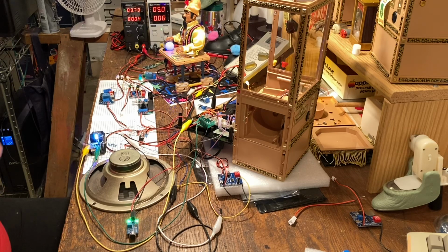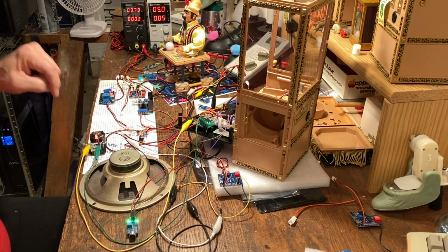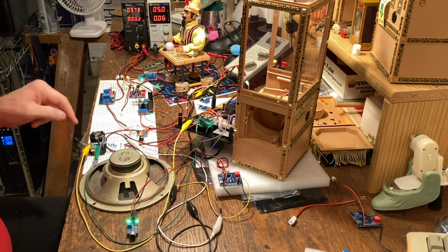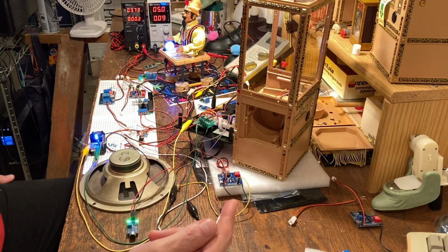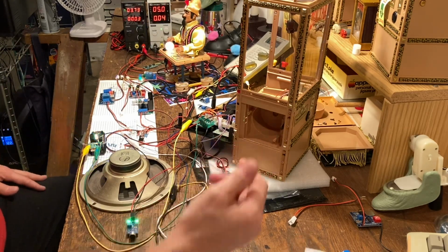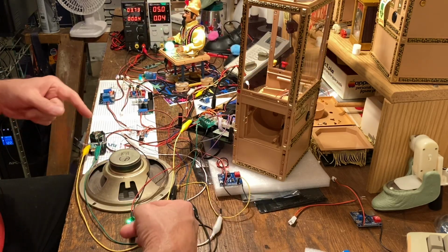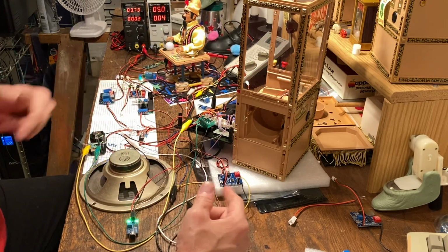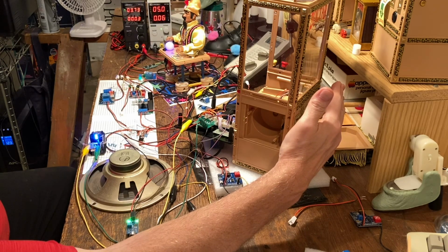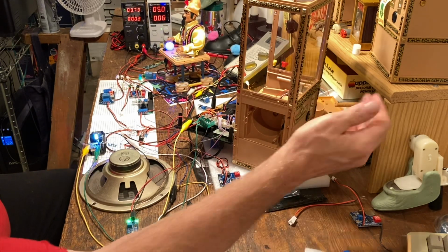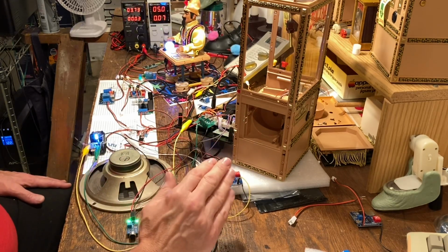Okay, so I tripped him by the photocell. When I put my hand over that, it drops the resistance to the photocell. The photocell trips that circuit. Now I'm going to reach up front and do it IR. We'll do it infrared on the front. So that's the third method, and all this is hooked up on the same sense line on the attract. Okay, I just tripped him on using the IR sensor that he has built in.